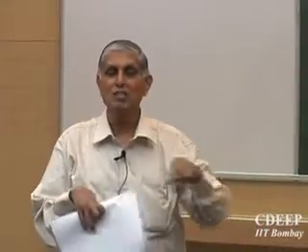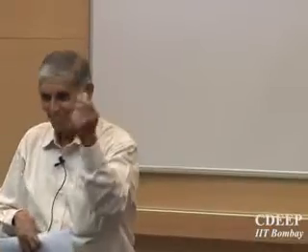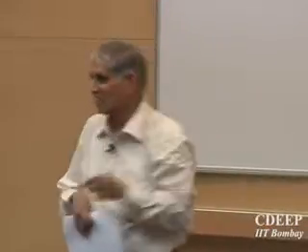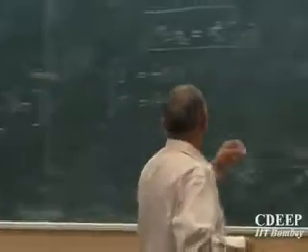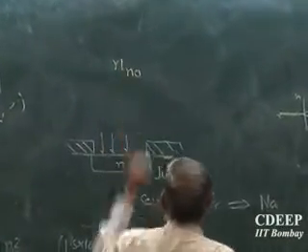This issue is that this number is very crucial because transport efficiency matters, and diffusion transport is essentially governed by minority carriers. Is that clear? That will dominate all bipolar processes. Whereas in the case of a MOSFET, the current is always due to majority carriers. And there we say 10 to the power 16 is important. So in two devices, this majority and minority role may vary. Therefore, these numbers are very crucial in all device analysis: how many majority carriers and how many minority carriers. So many a time, we also give a symbol N sub N0. What does that mean?